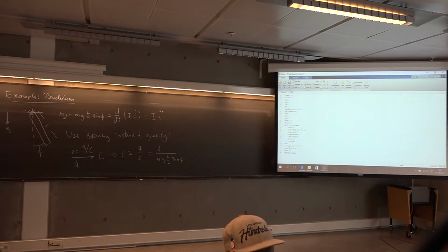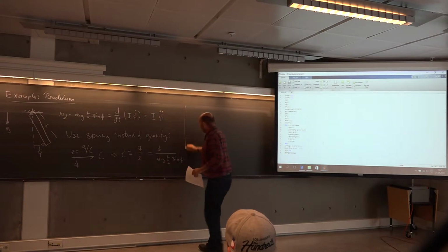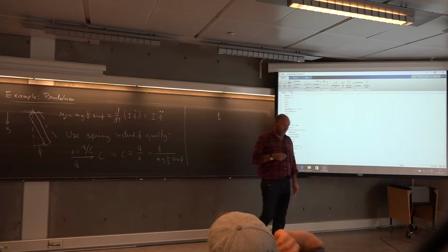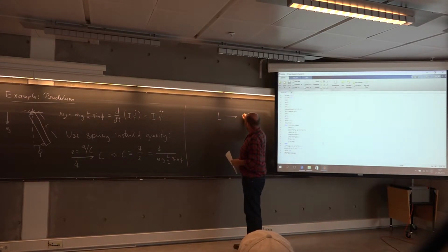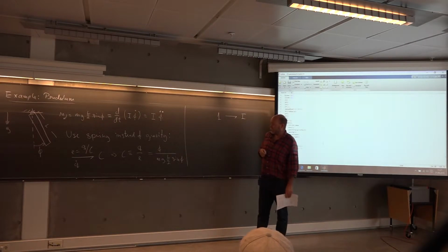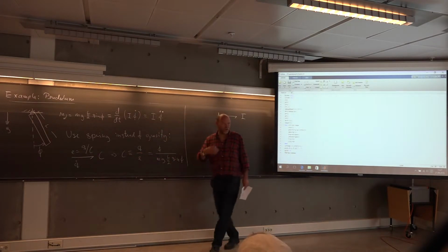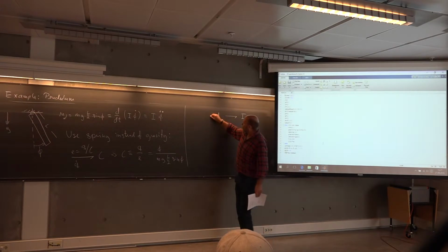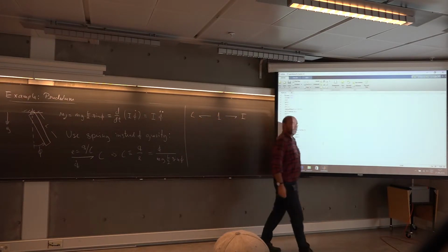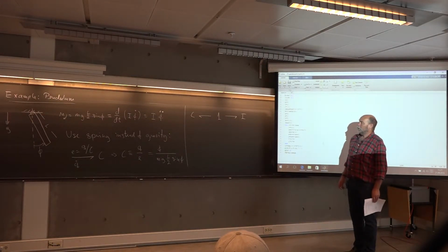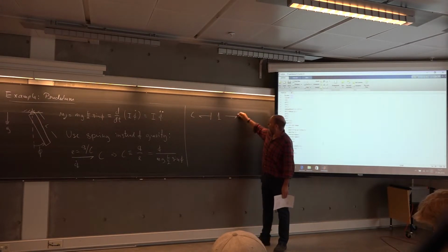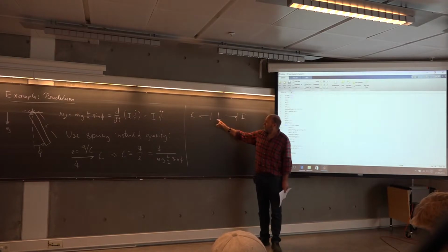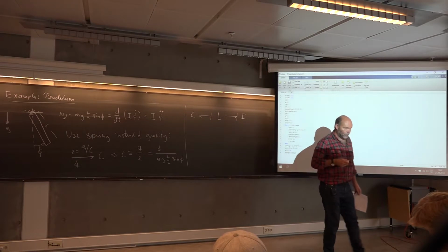What will the bond graph here look like? Well, you have one rotating part, one moving part with its own unique rotational velocity. So yes, you start with the one junction. This one junction has mass attached to it, so you have an I element. And now we have added a spring instead of a source, which was a little bit messy to include here. So I have my bond graph like this. That's it. And is it causal? Well, yes, of course it is. I would like the causal stroke here for the C element and here for the I element. And yes, for a one junction, this is the correct integral causal strokes, the way we like it.